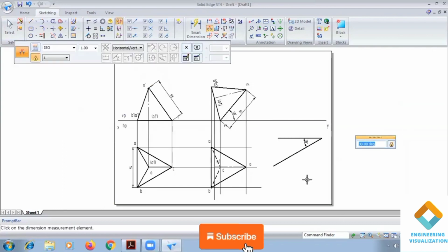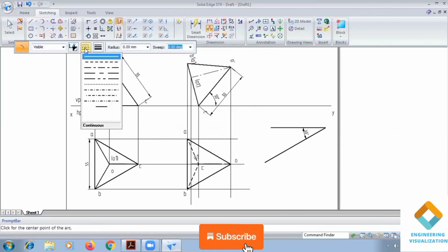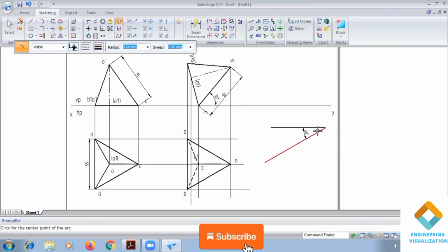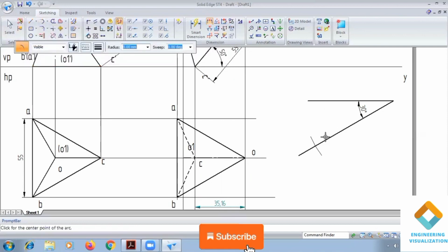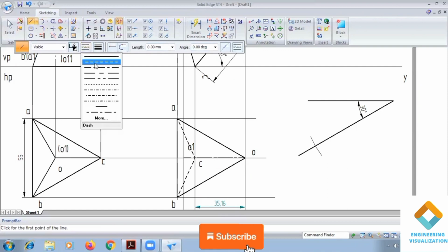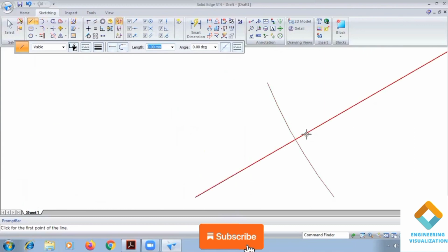Now here you need to use the slant edge length, that is 55 mm. So go to arc by center, take 55 mm length and cut the arc. Now draw the locus line. Another slant length we have is 35.16, so these two lengths are required. One length we have already drawn. Now we need to draw a locus line here, a horizontal dashed line.